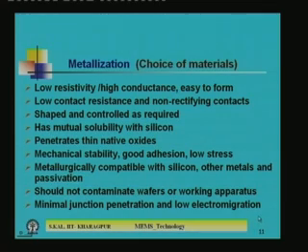For that you need a metal film, and the metal film is etched, and as a result you can get the interconnect lines. So, now when you go for metallization, there are certain thumb rules to select the metal film which will be suited for your application or your device.